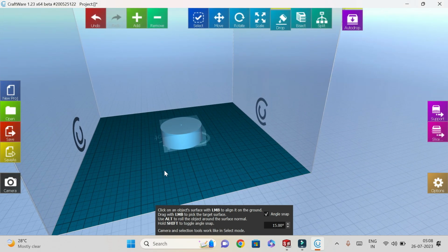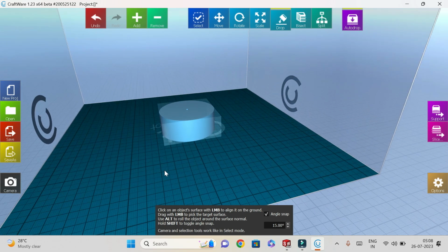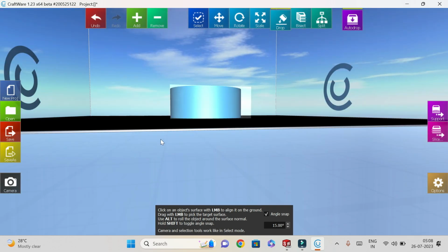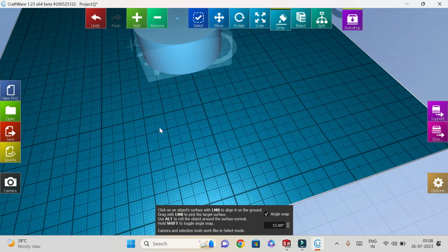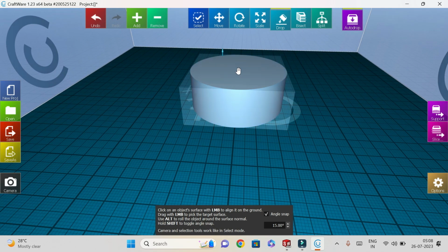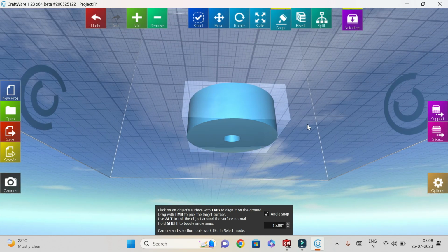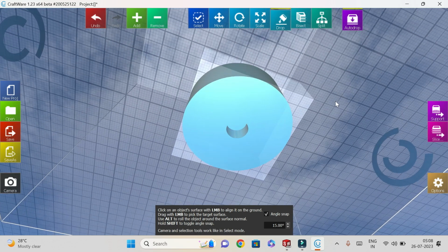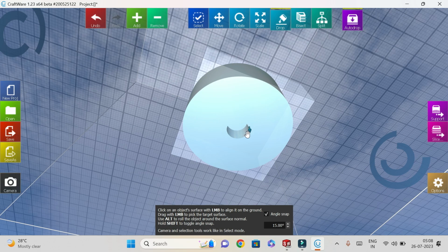So this is our required geometry, and one important thing is that there will be some issue of gravity while printing. This part can be easily printed, there will be no gravity issue, but gravity will lead to a problem at this location, because when this portion is printed, there will be a requirement of some support. Okay.